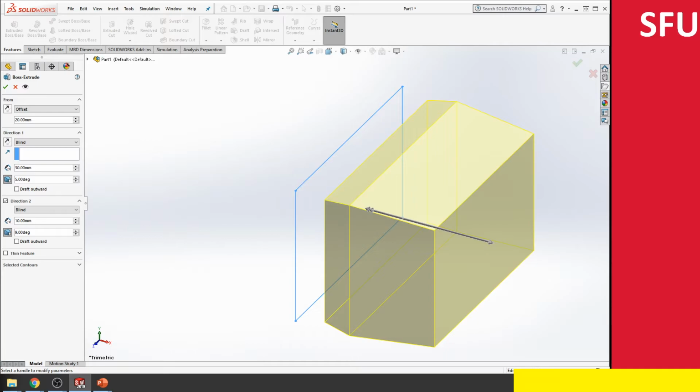The reason you would have an inward draft is when you're manufacturing the part, say if you're casting the part, it's useful to have a slight angle so that you can pull the part out. Imagine the cupcakes that you buy. If you're baking cupcakes, you have a taper on it, which would conceptually be the draft. Then you can take the cupcake out of your baking tray. I know baking isn't the most relevant thing you would think about in an engineering drawing, but nonetheless the principle applies all over.